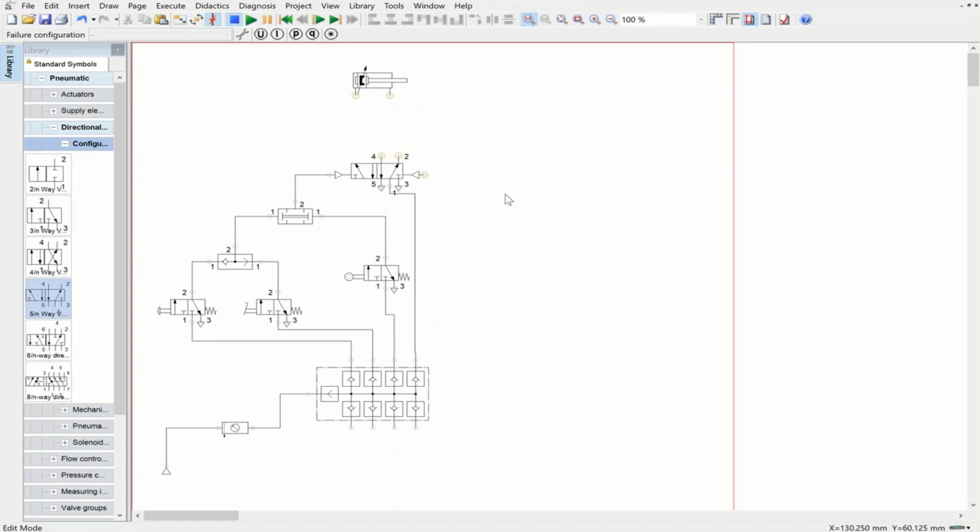And for both retraction and advancing, therefore we need to have throttle check valves, and we would have the capability of changing the opening level of throttle check valves. And once we have this capability, basically we can adjust the speed of the actuation here, right?